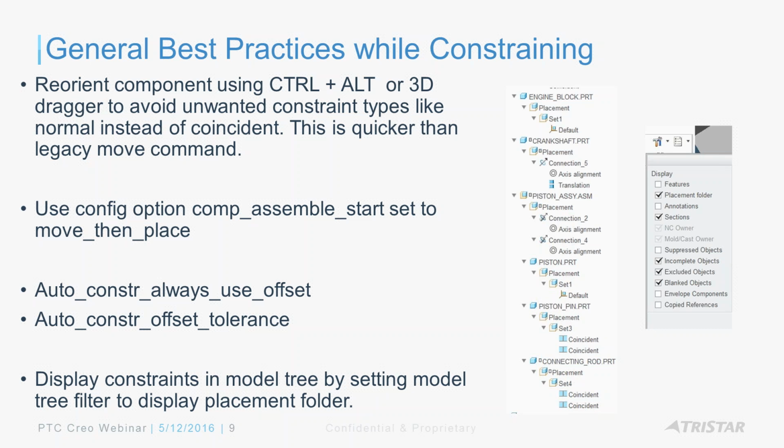So the motion using Control-Alt, I'm sure some of you may have used it, but instead of the old move command, if you hold down Control-Alt or just use the new 3D dragger, it's going to spin, pan, zoom your component while the assembly stays put.